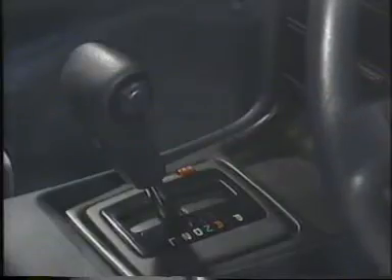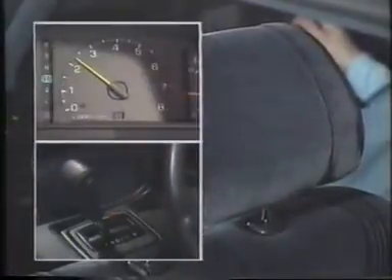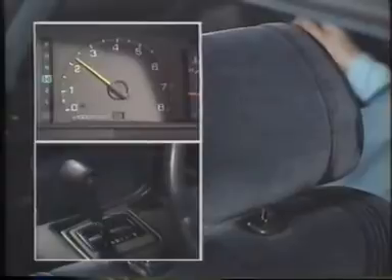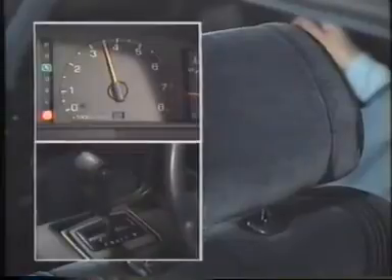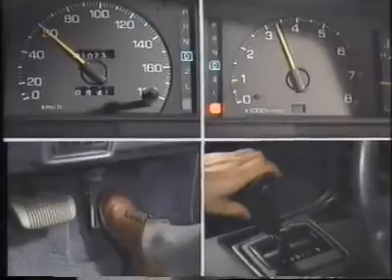The shift lever position and the engine speed often have effects on vibration. In this case, the shift lever position and the engine speed seem to be unrelated to the problem, as the vibration is still felt when you move the shift lever or change the engine speed. Now, let's summarize all the test results.